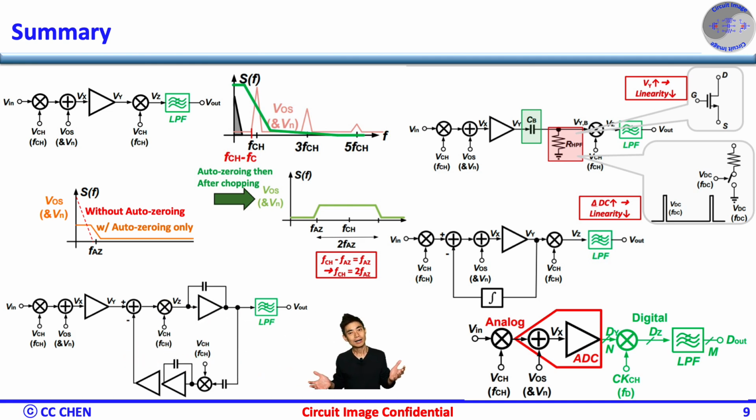The last one is digital filtering by putting the demodulation and filtering after the ADC, which may require lots of calibration to mitigate the ADC's impairments. Again, the digital filter should have a good notch at the chopping frequency to filter all the ripple pretty well.